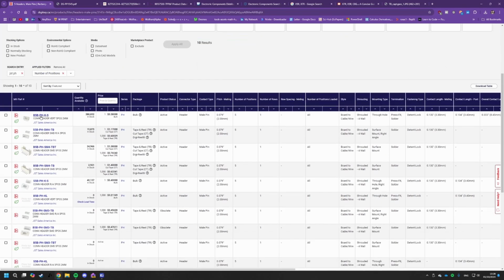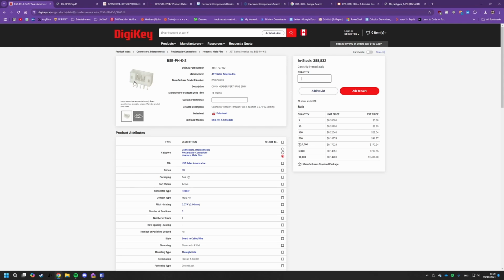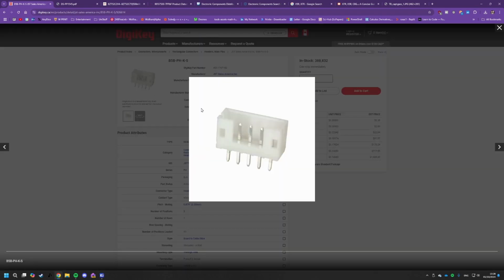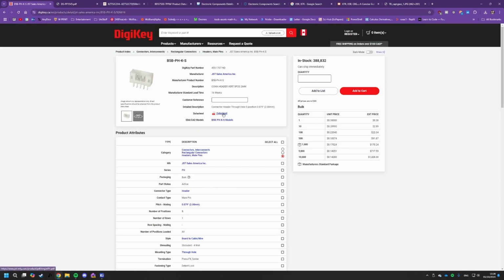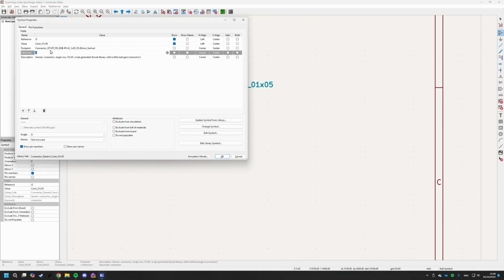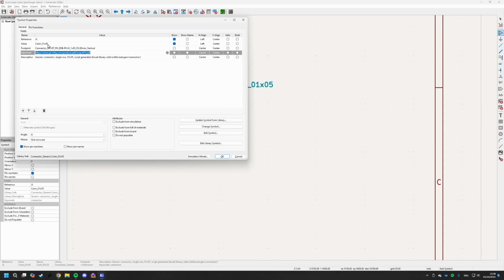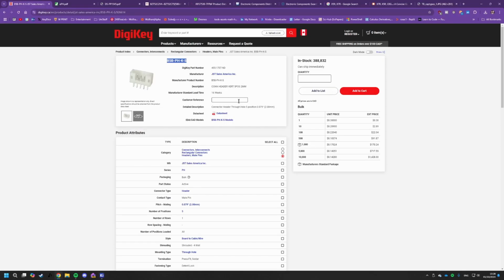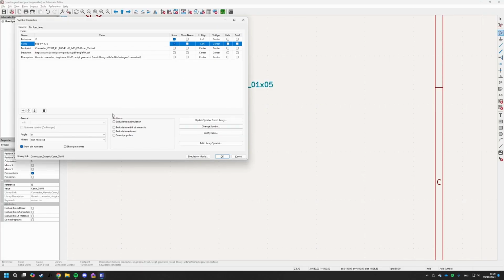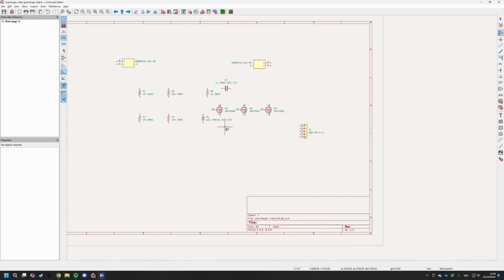We got quite a number of them, but this one would probably be the best fit. So if we use a datasheet, also update value and add a description. We'll be done editing this symbol. Cool.